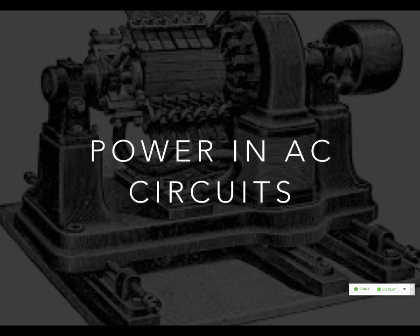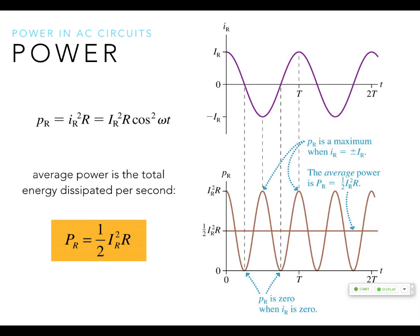That's a very abstract way of saying it, but whatever you're building, you want to be aware of this resonance, because remember, power is I times V, current times voltage. But remember, in this case, it should be instantaneous current times instantaneous voltage. And if you use your V equals IR stuff, you end up with something that looks like this, okay? So the average power is going to be the total energy dissipated per second.